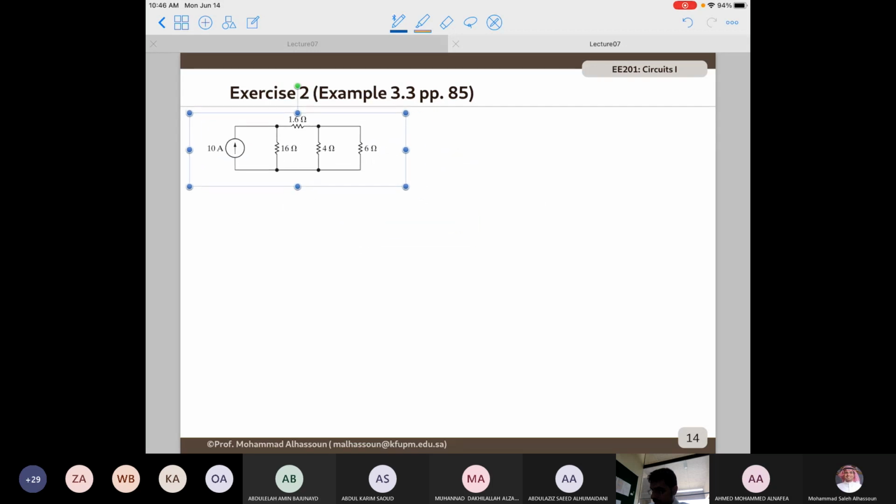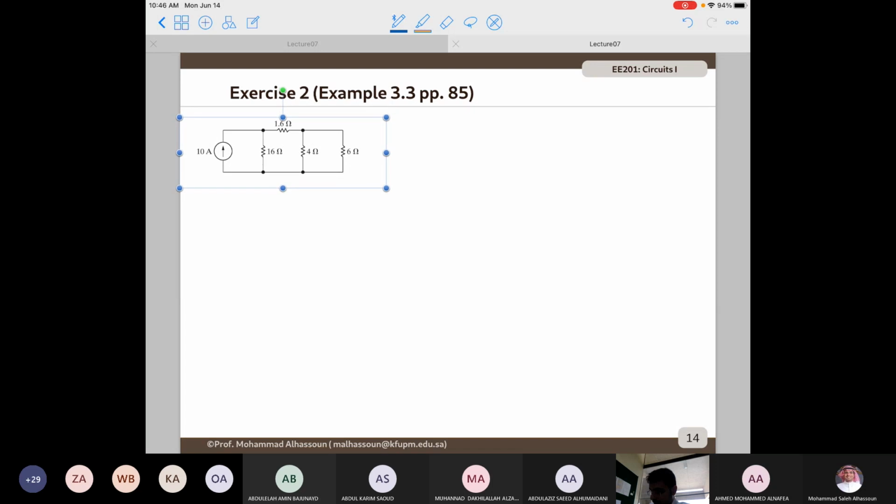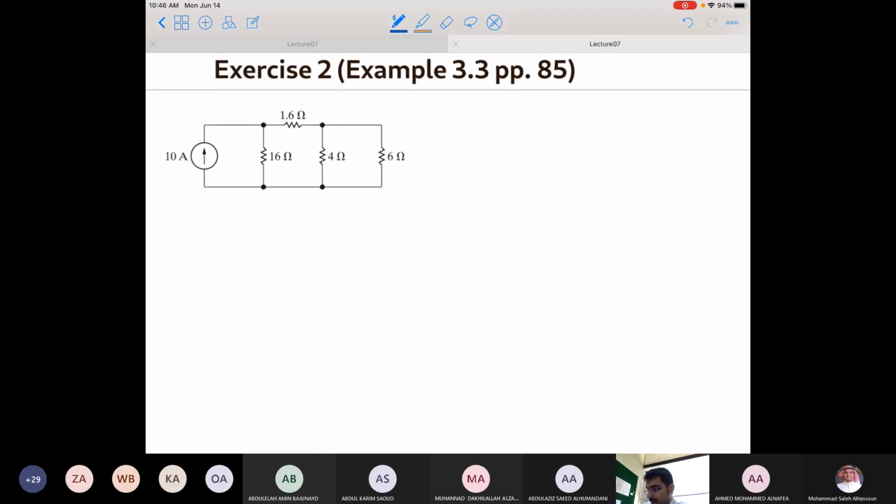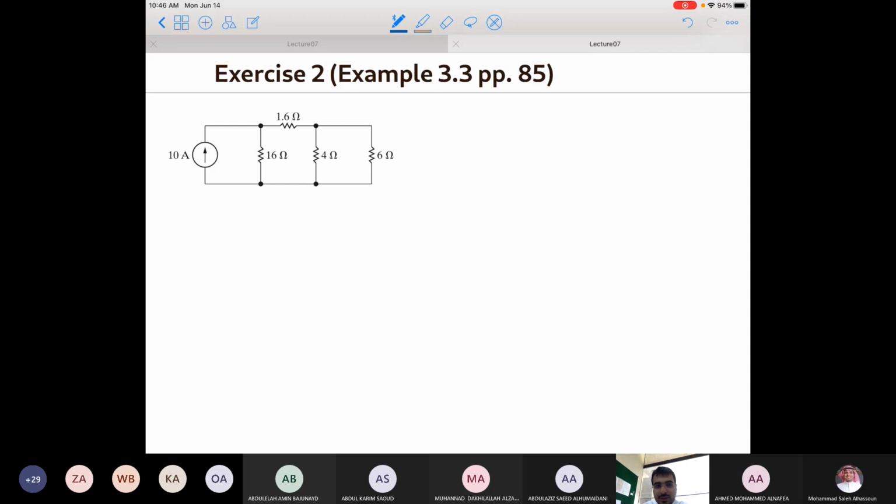So in order to find the power, you need to find the current, because you know the resistance or the voltage actually. But in this case, it's better to find the current. Not really, actually, you can find the voltage as well. But anyhow, this depends on the current divider circuit. So we are assuming that we're interested in finding the current. If I call the current flowing through the 6 ohm resistor I naught, I need to find I naught.